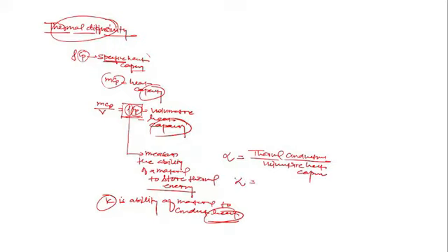This is called thermal diffusivity, a very important property, and this is K upon rho Cp. It's a very important property in the study of heat transfer, and its unit is meter square per second. You can check K by rho Cp. And what does it measure? Anyone?